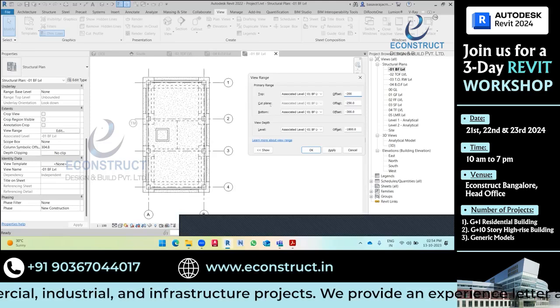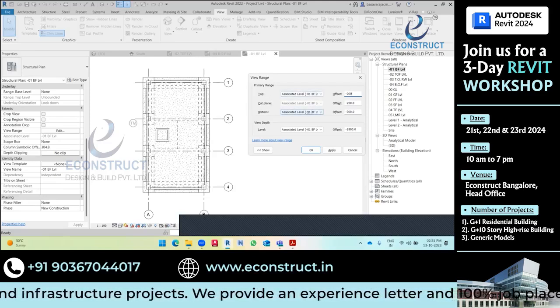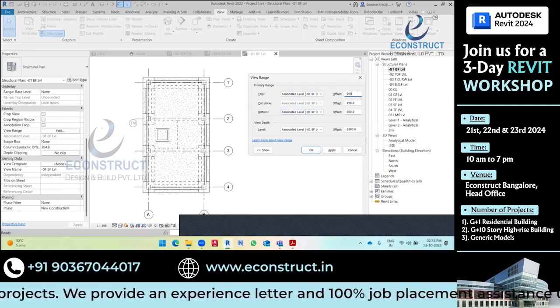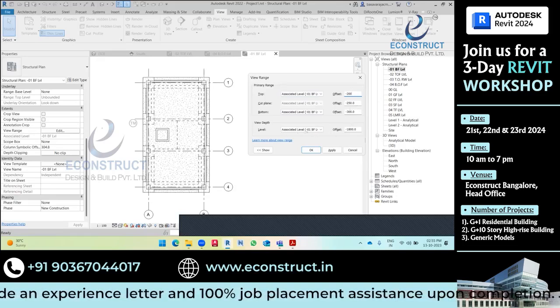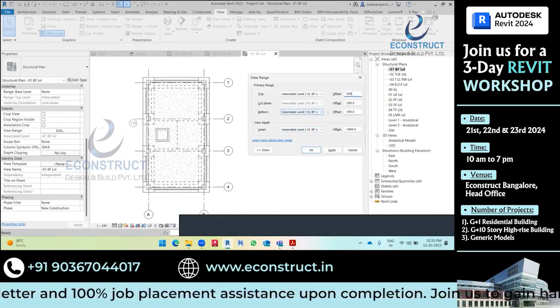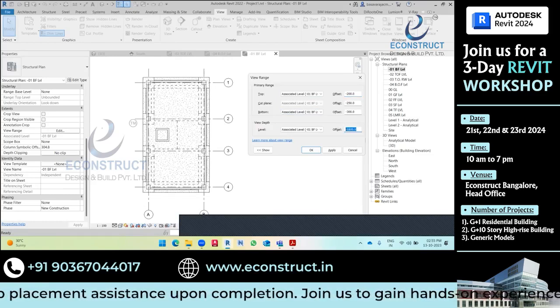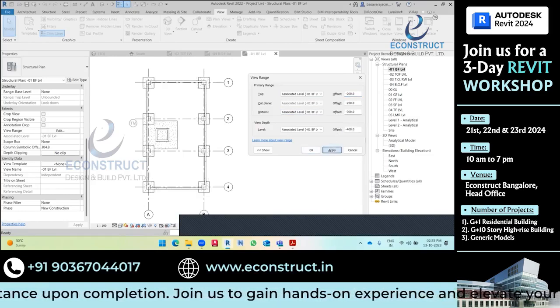The top plane should always be above the cut plane and the bottom plane should always be below the cut plane, so you should enter the values like that. And the view depth level should always be below the bottom level or in line with the bottom level. So this one I will take minus 400. I will click on apply.